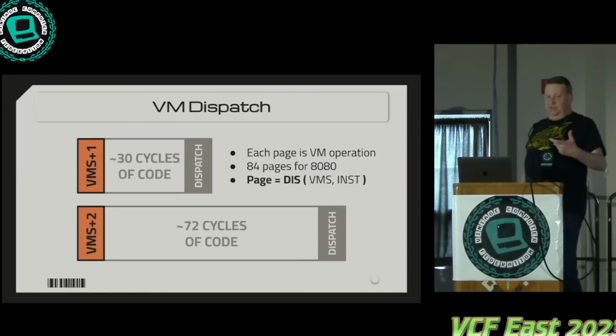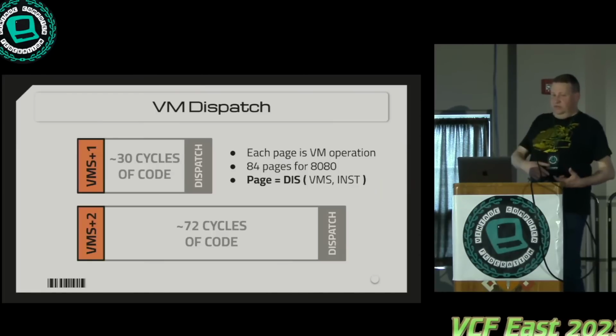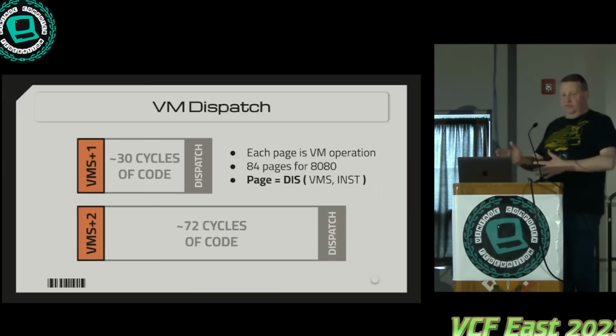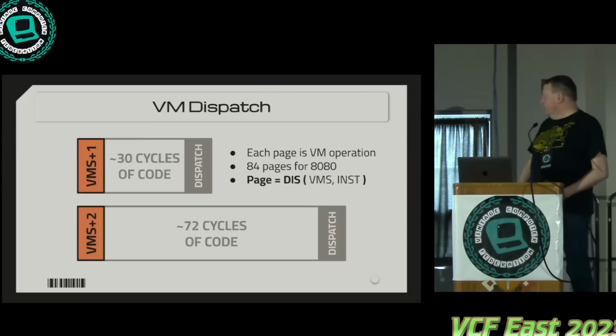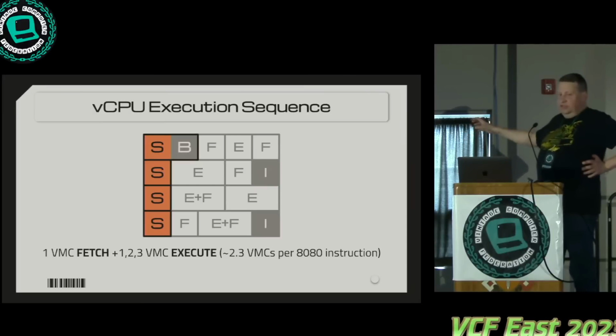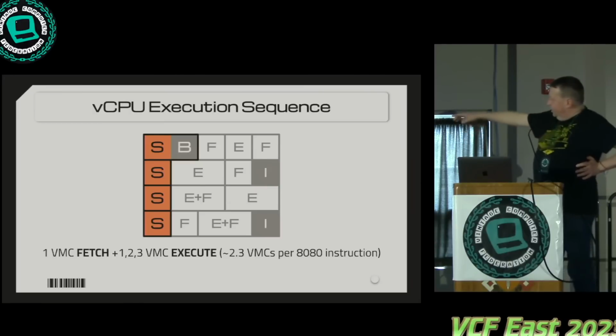So it takes the 8080 machine code instruction and the state, and then it determines whether it has any cycles available to execute that code, or whether you've come to the end of the line and it has to do a horizontal sync. That's all pre-calculated and loaded into the ALU, and it uses that to drive the virtual machine. And this is actually what that execution sequence looks like. In this video mode, we have these 4 sync pulses.